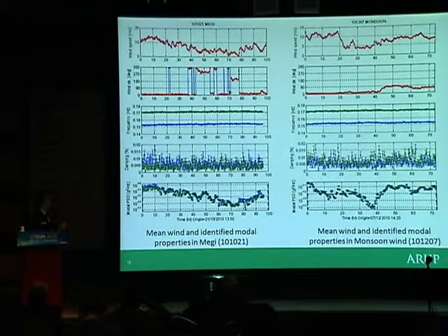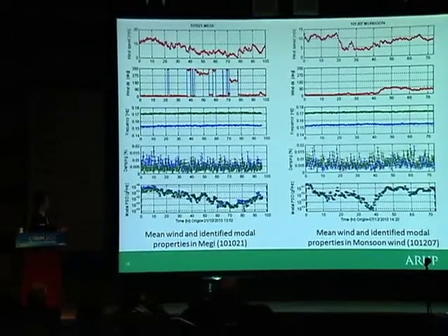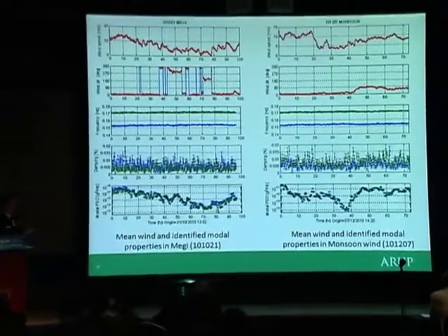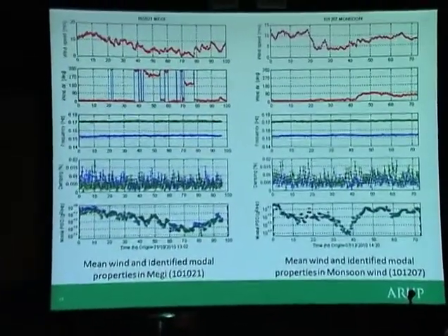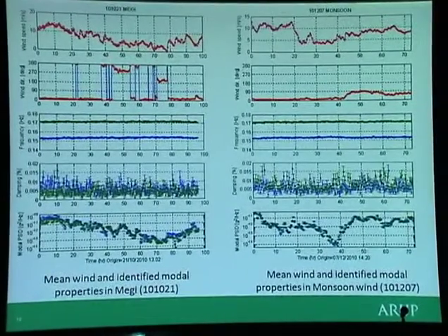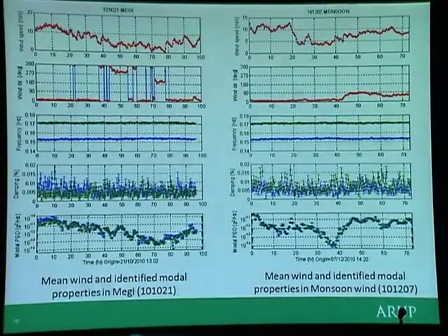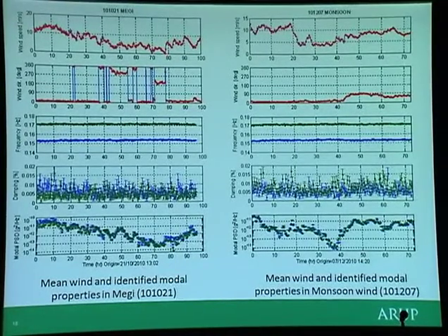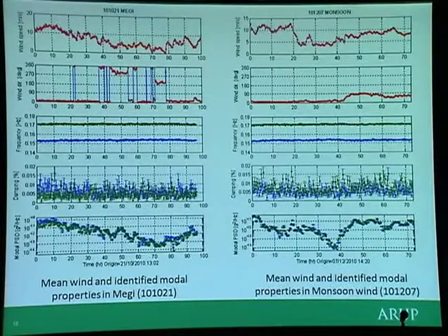If you look at the high wind speed region here, the damping ratio is a little bit less than 1%, or between 0.5 and 1%. Again, those winds are relatively small because we're talking about, say, less than 3-year return wind. We haven't had a very big wind event yet, so we're waiting for the next big typhoon.